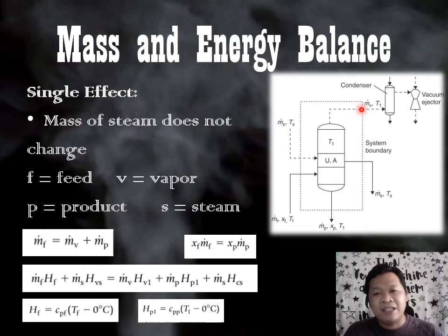Note, sabi natin, di ba, we use steam tables kung tubig ang pinag-uusapan. And then, since yung feed at product ay hindi naman pure water, they could be anything from juices to tomato paste or what. So gagamit na lang tayo ng calculated specific heat values or predetermined specific heat values. So dito magiging useful yung mga equations natin on yung mga MC delta T.